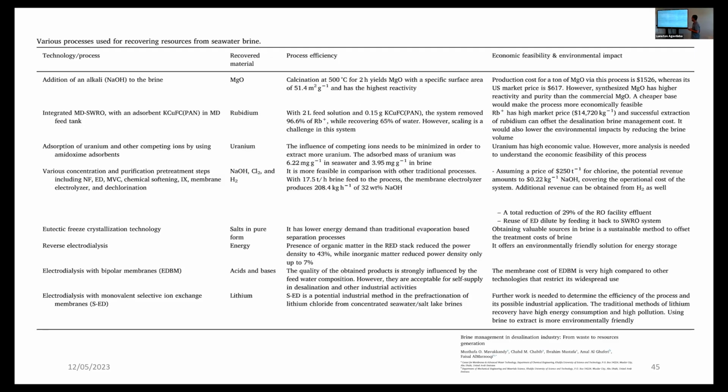You have to understand that, again, you can find in the literature very different types of techniques that can be used to recover. For example, reverse electrodialysis, a technique very much explored here at Wetsus. There are many different real-scale systems that are already using these salt gradients to produce energy, for example the RED stack system. You can also, for example, use electrodialysis for selective ion exchange and recover lithium.